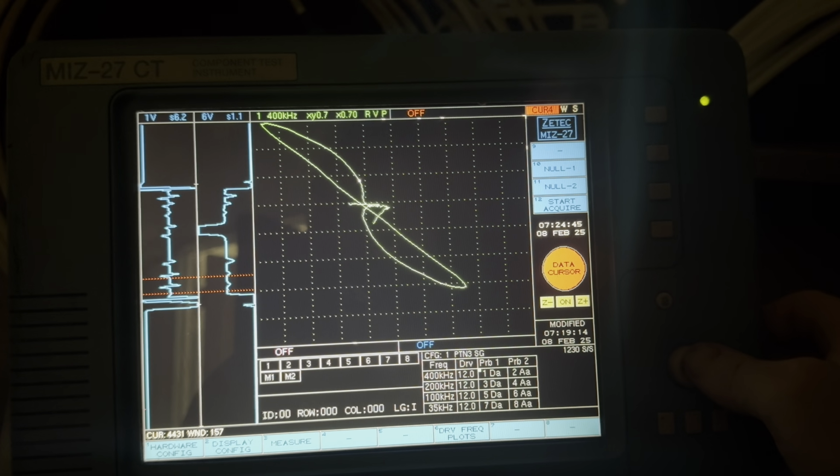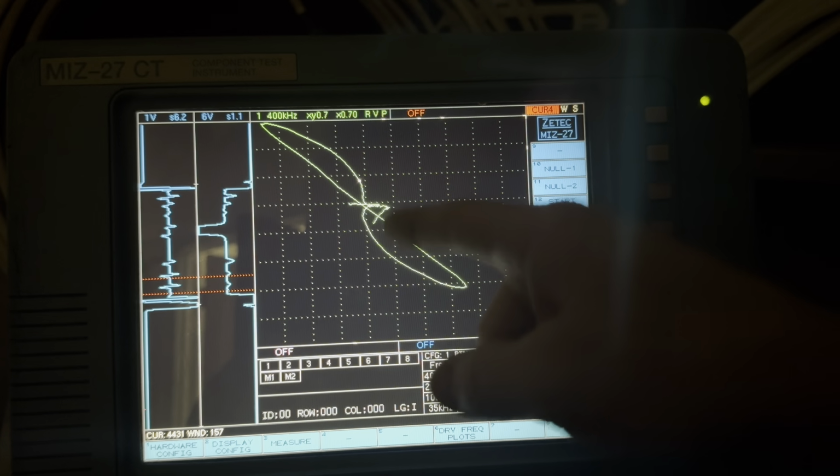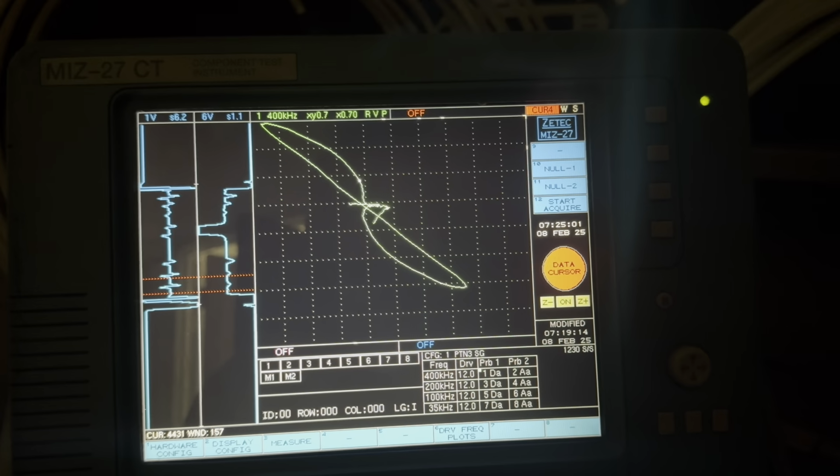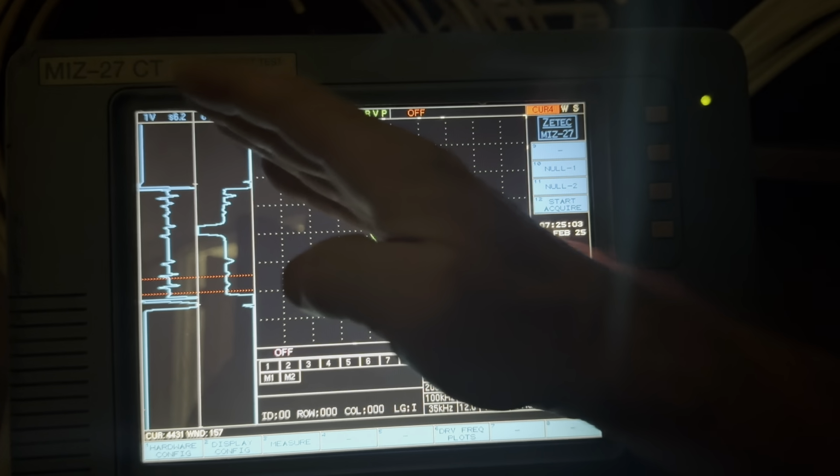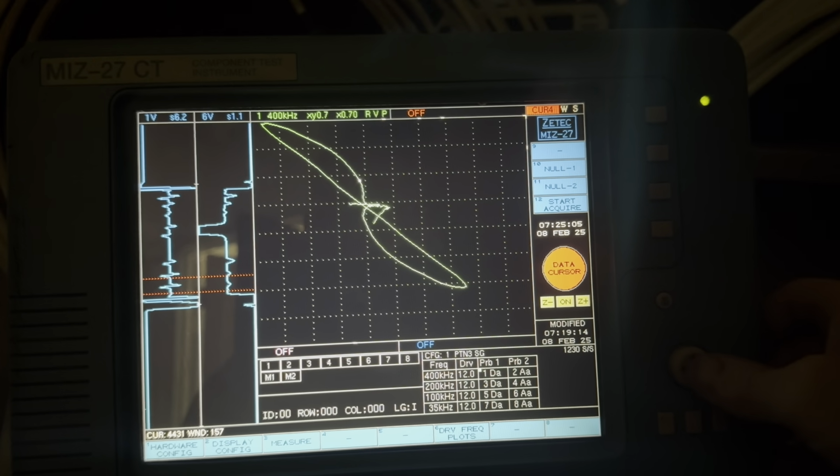Okay, phase lag, 100%, set to 40 degrees. That doesn't mean that a through-wall defect is always going to be exactly at 40 degrees. Could be 35, could be 45. But the general theory is that if you set your through-wall hole to 40 degrees and you have a big signal that comes up to 40 degrees, you may want to investigate that as being a potentially true defect.